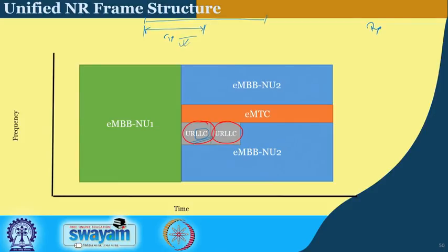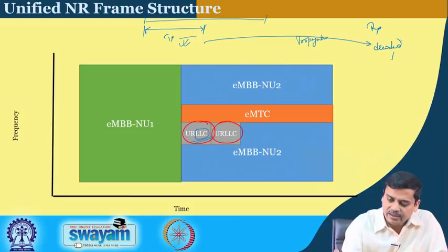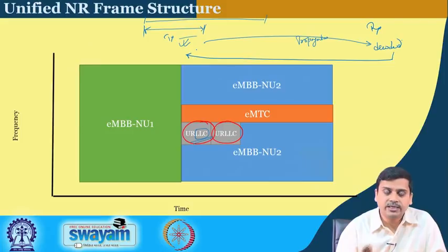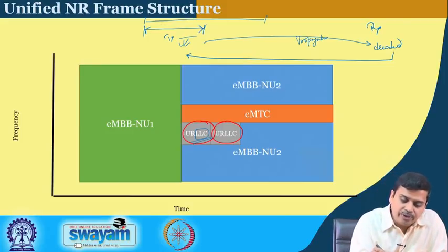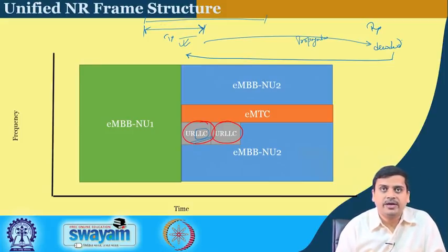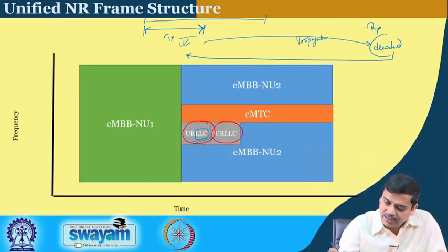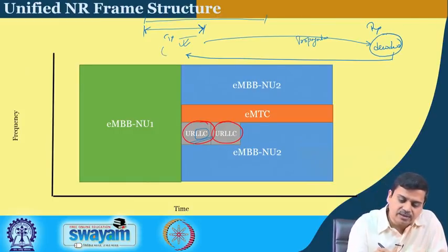So, it has to be generated at the transmitter, go from transmitter to receiver through propagation, be decoded at the receiver, and then be sent back to the transmitter. So, the basic unit which constrains this entire flow is the slot unit, which is now addressable. Earlier it was a subframe unit, plus there is this processing delay at the receiver side as well as at the transmitter side.